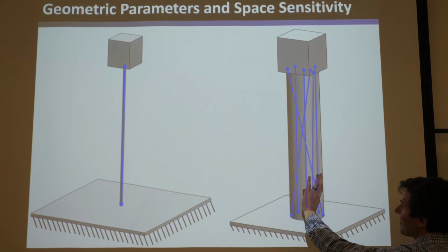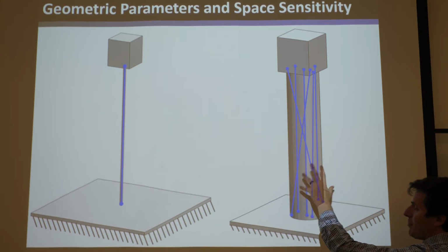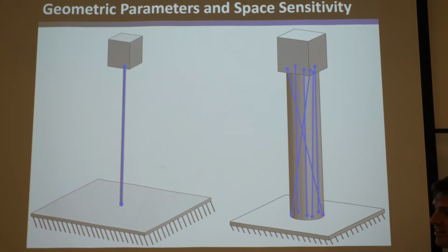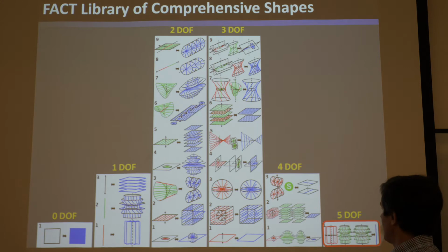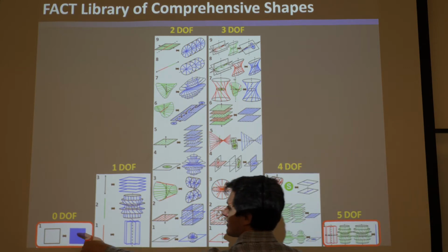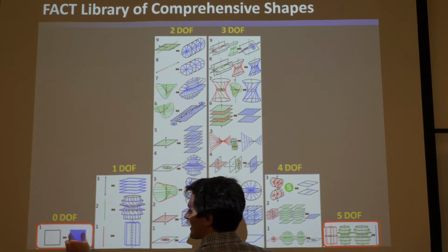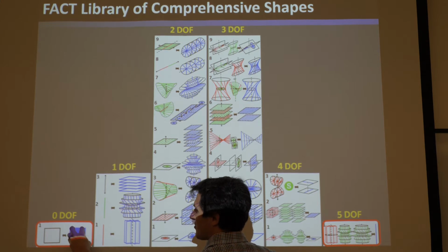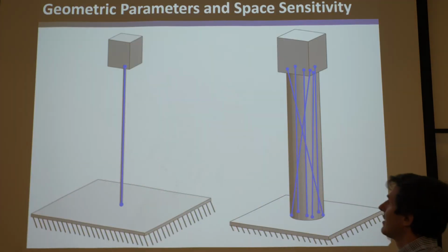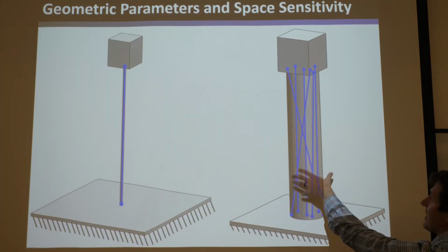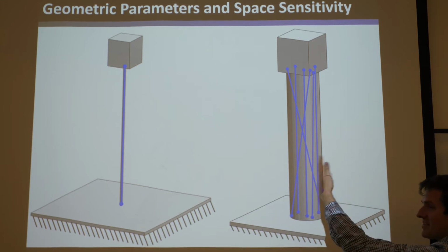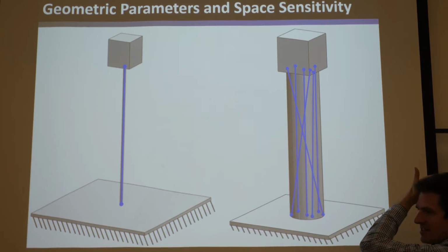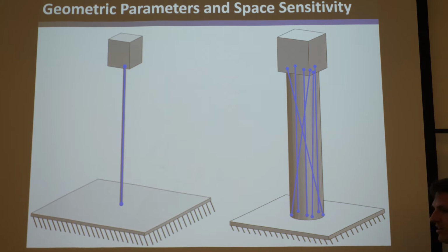And so sure enough, this is a parallel element. And sure enough, there's enough independent blue wrenches in there that it would be 0 degrees of freedom, so 6 independent wrenches in entirely filled blue space with no degree of freedom would be this guy. And so it would be locked up. It would be an order of constraint of 6. You wouldn't say it's over constrained because it's an element, okay, and it's a parallel element. It would be an order of constraint of 6, and this would be totally exactly constrained. This wouldn't be able to move.